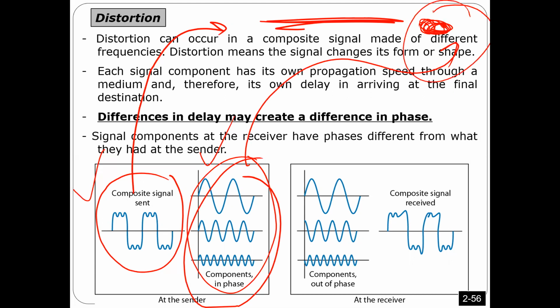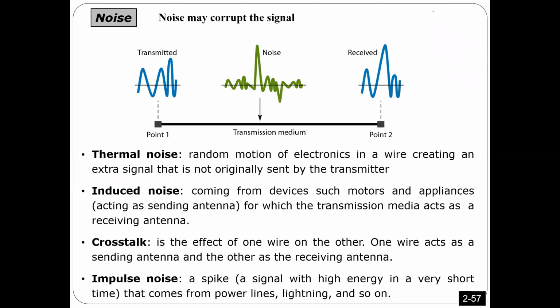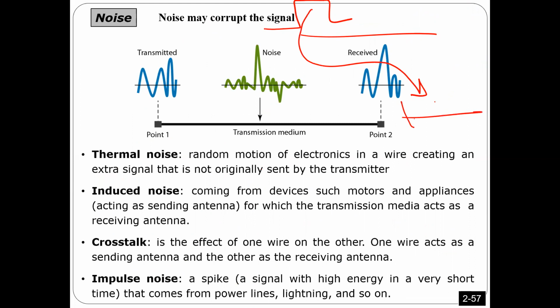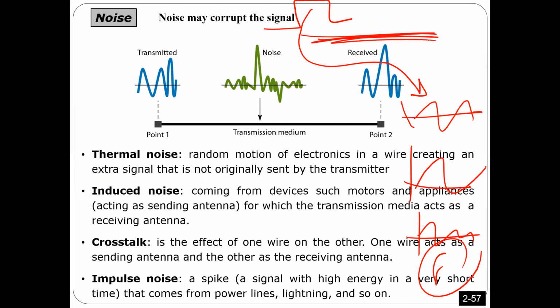You understand what I'm saying? You remember when I told you before, if I want to transmit a square wave like this one, this is difficult. This is challenging. This is because this one has infinite frequencies, infinite until a frequency is infinity, and there is no medium that can pass infinite frequencies. You got what I'm saying?